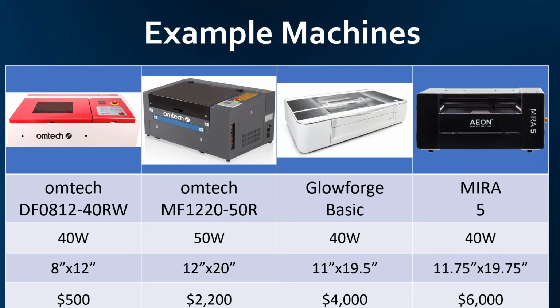Something about the Glowforge, though, there are certain features of the Glowforge, given that I own one. They have a feature where you're supposed to be able to just draw on a piece of material and then put it in the machine. The machine will see the drawing, and then it will cut that drawing out for you. I have never really gotten that to work very well. You typically have to have really thick, dark lines for the camera to pick it up, and the parallax is pretty bad, which is to say the camera inside the Glowforge has essentially a fisheye lens on it so that you can see the whole base of the machine. But the parallax correction doesn't work super great, and so what comes out doesn't quite match what you actually had. Now, for certain work, that doesn't matter.